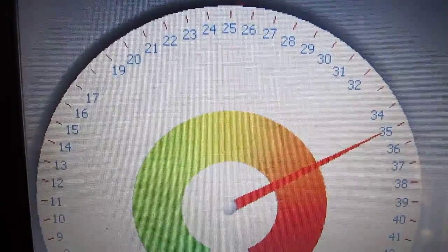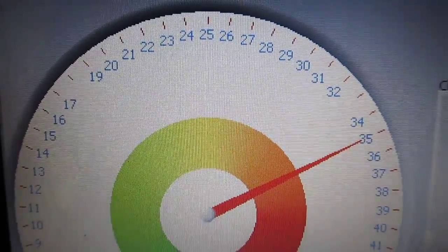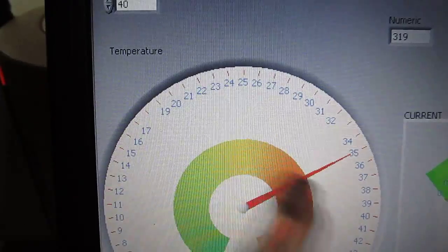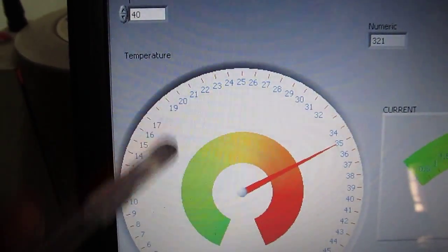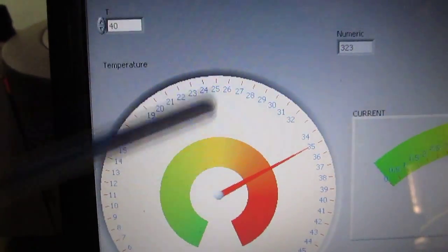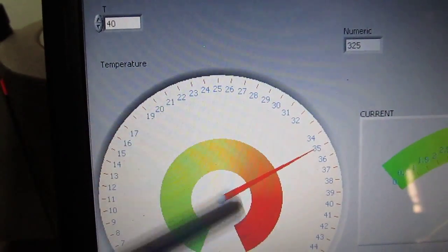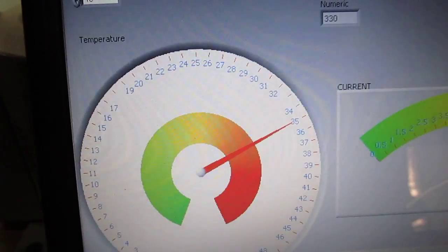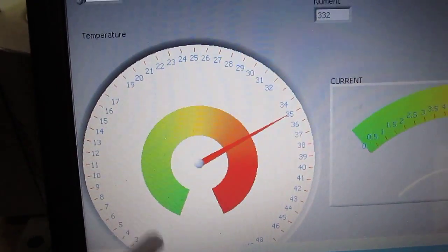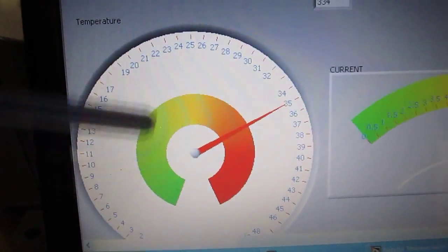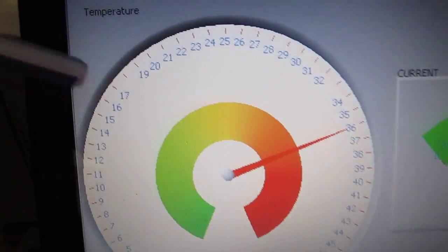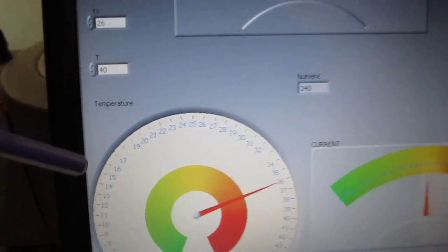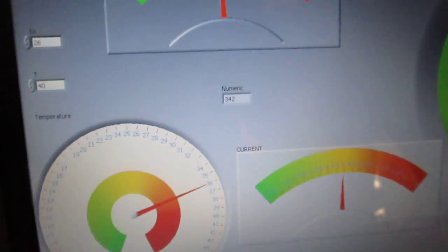In actual operation, whenever a fault occurs, there will be an enormous amount of current that will rapidly raise the operating temperature of the machine. Even in those conditions, this is going to shut down the motor automatically, so that the operator in the control room knows there is some kind of fault because of which our motor is tripped, and the indicator shows that the relay has been tripped because of overload. And the operator will come to the motor and resolve the problem.